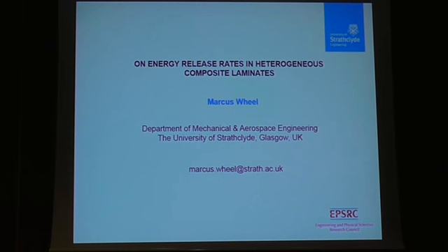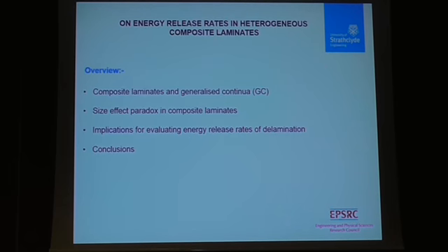Maybe by trying to explain the title of my talk, what I'll do is give you an overview of what I'm going to discuss in the first slide here. What I want to do is talk about composite laminate in the context of generalized continua, that is, materials that exhibit a distinct size effect when they're loaded. I also want to then talk about the size effect paradox in composite laminates. We'll show that the size effect depends on the order in which you lay up the laminate.